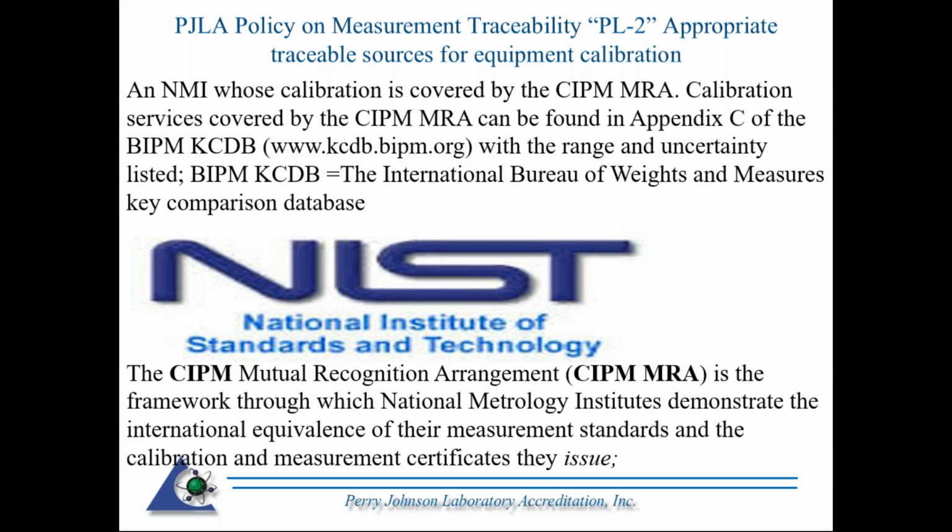You can go directly to the source, and those higher level calibration labs will often have a standard sent directly to the NMI, hence allowing them to have a smaller starting block to build on. When I say that, I mean their uncertainty or their CMC. If they go directly to NIST, or the applicable NMI, then they're going to build upon that uncertainty that was provided to them by the NMI.